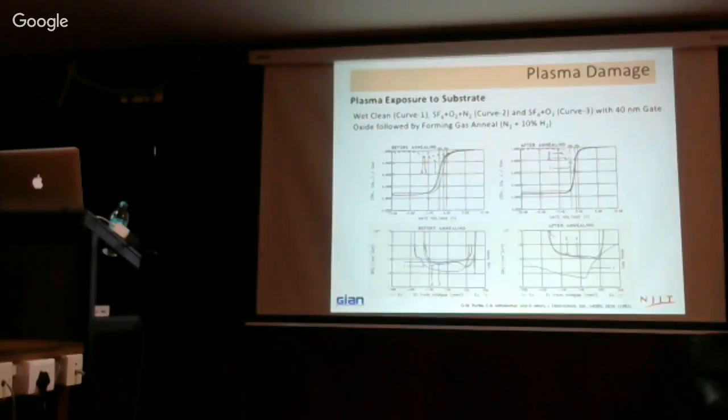Let's say on the back side you are making a contact. Can you make a little bit of P plus there? If not, then deposit aluminum and anneal it on the backside of the silicon substrate. Otherwise, it will form an aluminum to silicon barrier, and that will also create error.